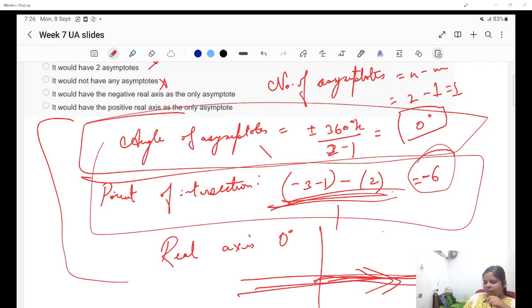Because the only way I find, without looking at the complex root locus picture, how everything should be arranged when it should be moving from pole to zero, is that my poles are on the left half of the s plane, my zero is in the right half of the s plane, and it should terminate there, and we should have it along the positive real axis as the asymptote. But I see this 0 degree should help us. Yes, ma'am. Zero degree, positive real axis.